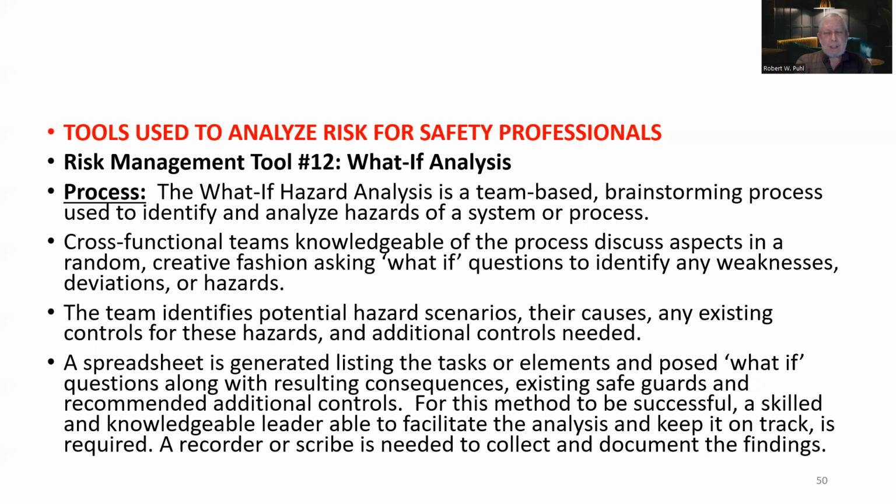So what happened in process safety management? We all got together with a cross-section of people. Obviously, the people who worked on the ammonia system, and myself and the safety department would be there, and usually our engineer. We already had a predetermined number of questions for this particular piece of equipment. Okay, what if this failed? What if this happened? What if this happened? And we'd go through each one of those and look at them and make sure they were okay.